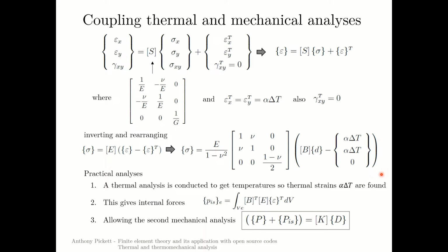Now, in a practical analysis, usually the way it's done is you do 2 steps. First of all, you do a thermal analysis to get the temperature distribution. And from this, you can compute these thermal strains. These thermal strains are converted to stresses here.